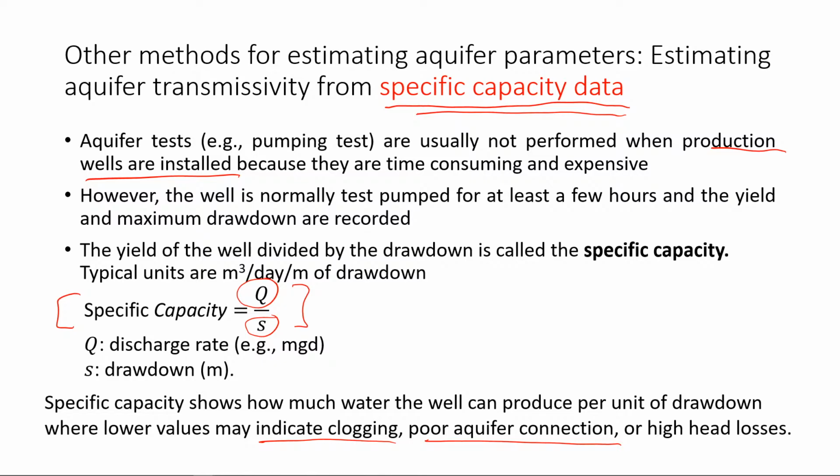So clogging can occur for different reasons. It could be fine sediments, or biofouling, or chemical precipitants that are blocking your well screen and the surrounding formation. For example, calcium could be precipitating, and that could plug the screen or the surrounding formation, affect your effective porosity and things like this, and that could restrict water flow.